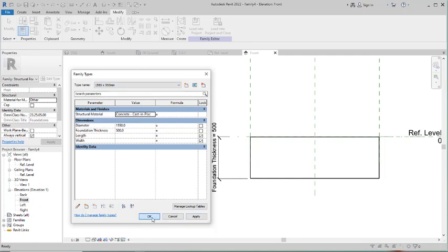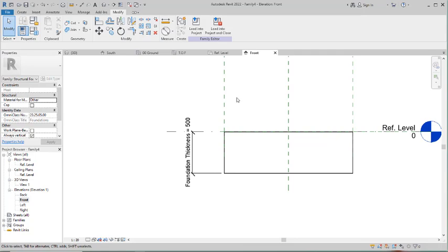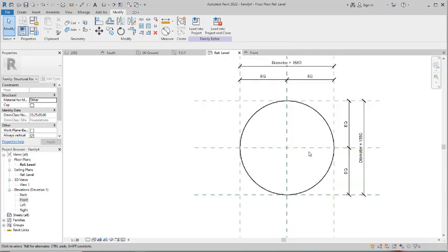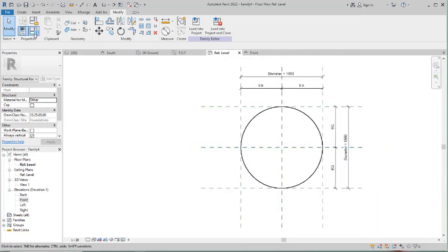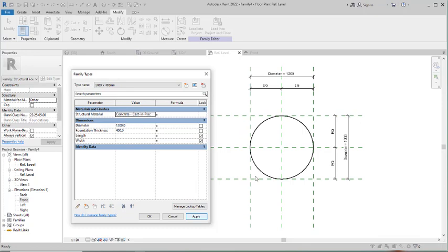So let's close this now. Okay, so we are about to save this. But let's go to the reference plane right there. So we are having this now. Click on this. So you can set as many presets as I said earlier, so you can navigate between these. You see it has changed over here: 1200 by 1200 by 300 millimeter has changed. And then if you choose this 1400 by 400 millimeters, that changes here, and then click on Apply there, it adjusts it. Okay, so everything now is effective.